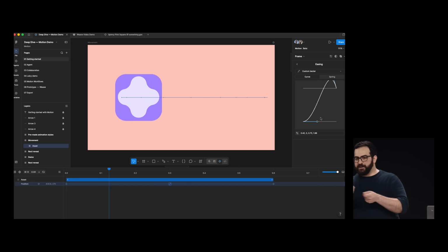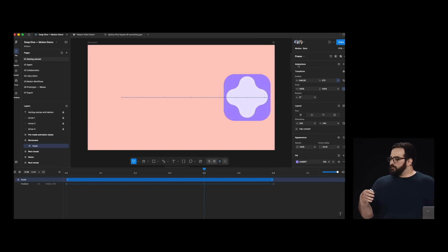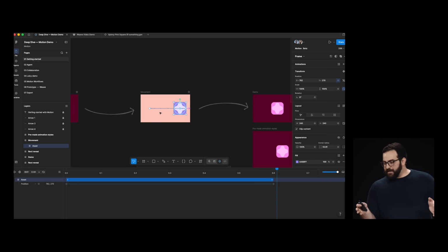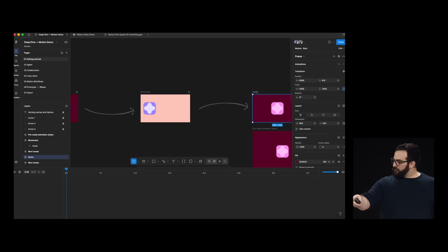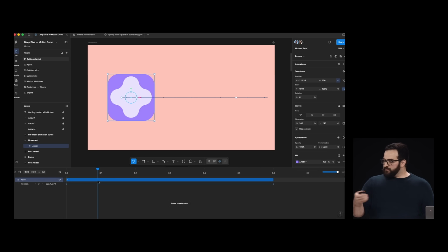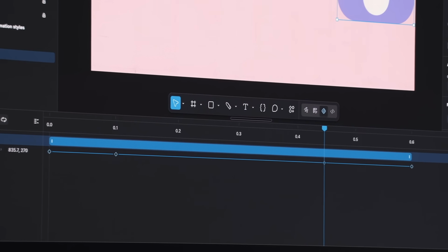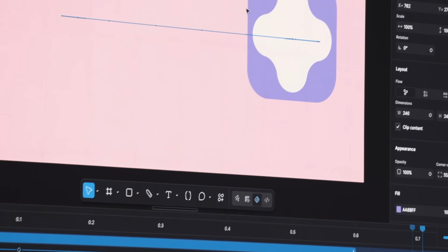Nice, so we can get a little bit of a spring there at the end. Fantastic. Pretty cool. Now, 2 keyframes does not an animation make, or it's a basic one, but we want to add a little bit more flair to this one. So how about we add a few more keyframes to that first animation, Daniela? Yep. And in here, we can move the playhead between those first keyframes, continue to move the motion gizmo, and add in a few more.